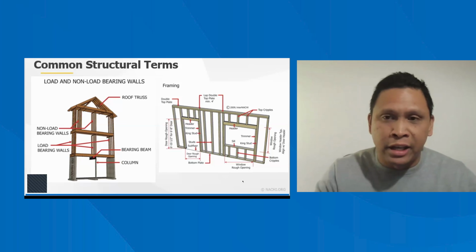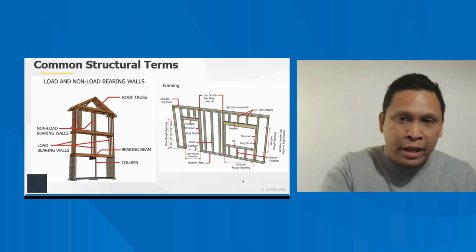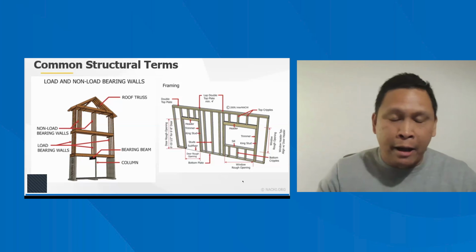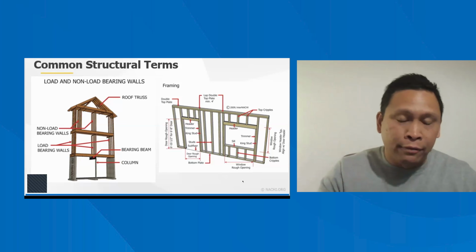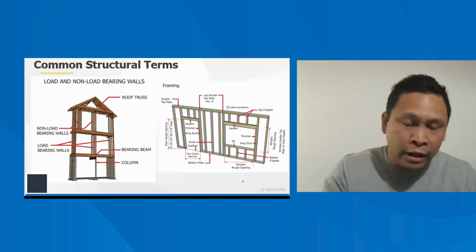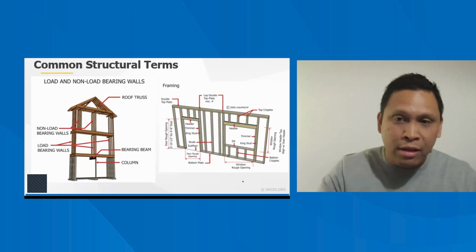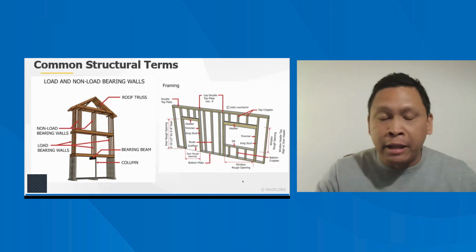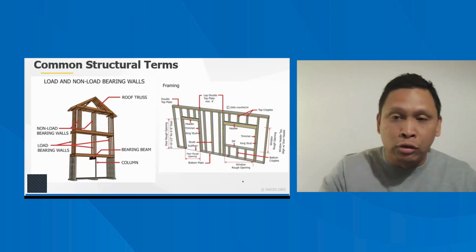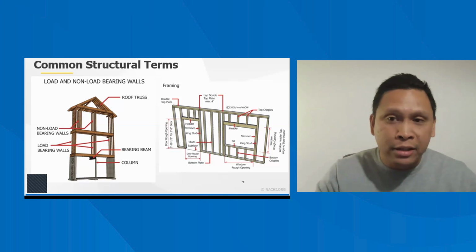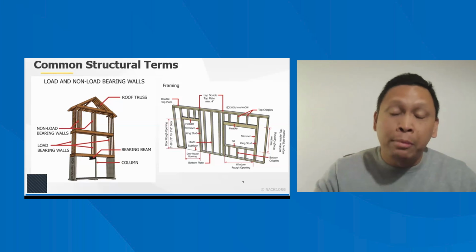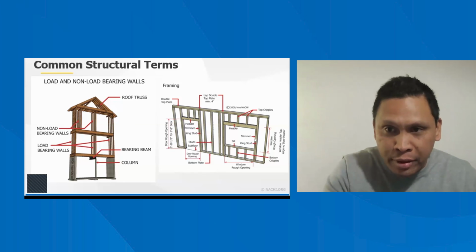Another common condition that I see is, when you look at the king studs, you want to take a mental note in terms of where those windows are placed in the home, and then once you're done with that particular floor, you want to go to the next floor right beneath it and look right underneath where you know that those windows are placed, and make sure that there is some type of support framing system there to help create that continuous load path from this king stud here and then down into the next floor.